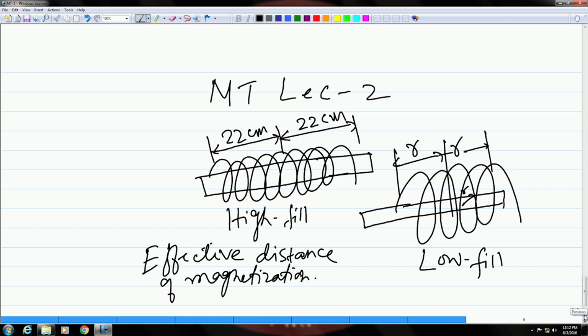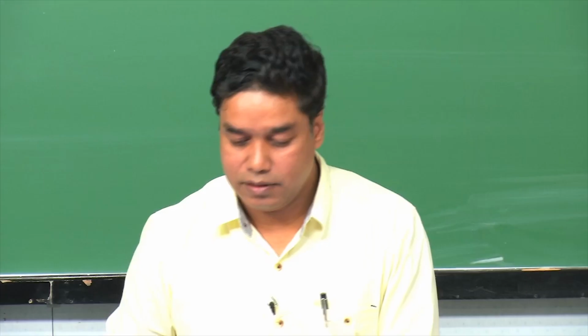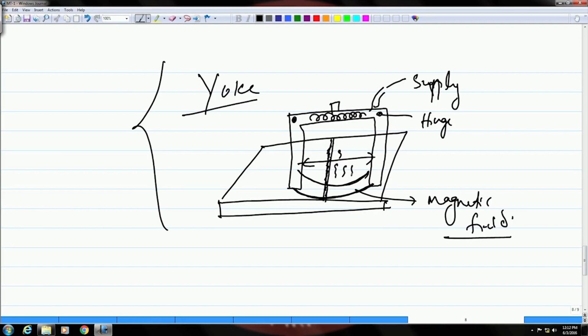So, this is how it is in case of a coil or a solenoid, and then we talked about this also, a U-shaped electromagnet, which is known as a yoke, that can also be used to magnetize the part. In this case the magnetic lines of force are across this. If you connect these two legs, along this line is the direction of the magnetic field. So, that means cracks lying perpendicular to this field will have the best visibility.